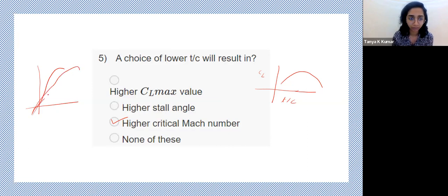Camber also, he's right. But for a lower aspect ratio, your CL versus alpha graph slope keeps reducing, keeping all other parameters the same. So if you have aspect ratio equal to 10, then 5, then 1, this goes on increasing your alpha stall. CL max is the same, but it pushes it across the graph, which increases your alpha stall. All other parameters are retained, just the alpha stall is increased. The aspect ratio and camber both contribute towards increasing stall angle.